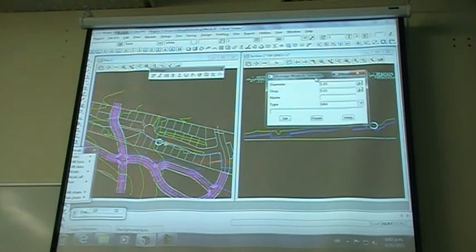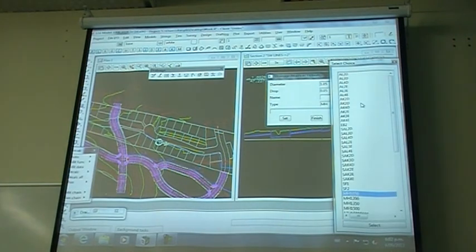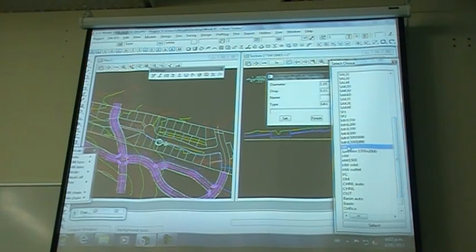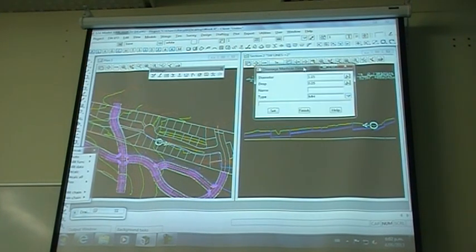And just make sure you pick a manhole, just MH, like we did last week. Under that pit drainage manhole defaults, just pick the type MH. The diameter is 1.05 and the drop is 50 mils.